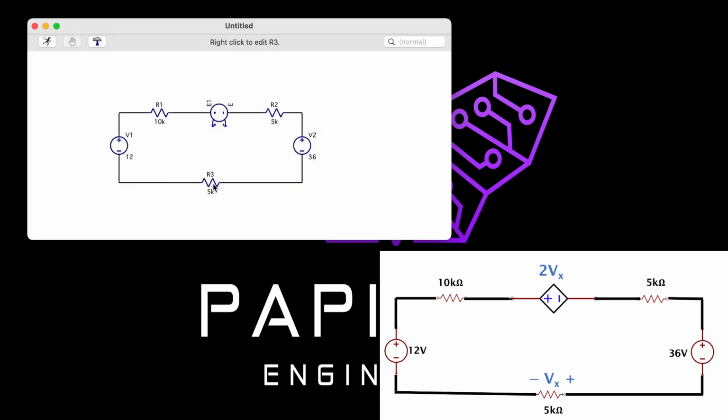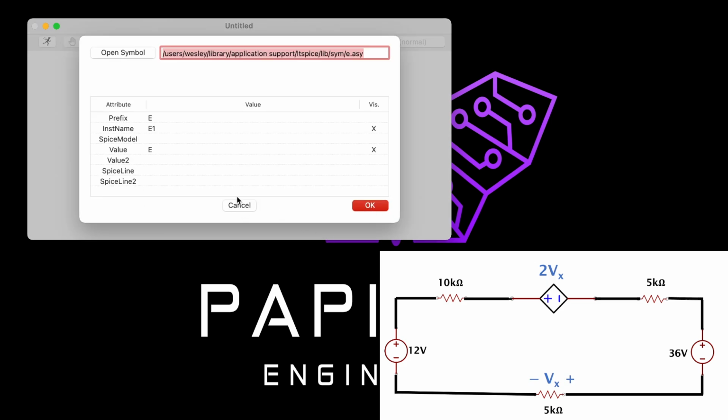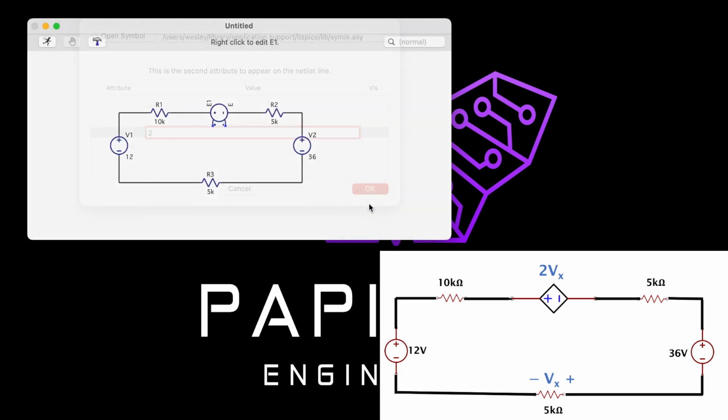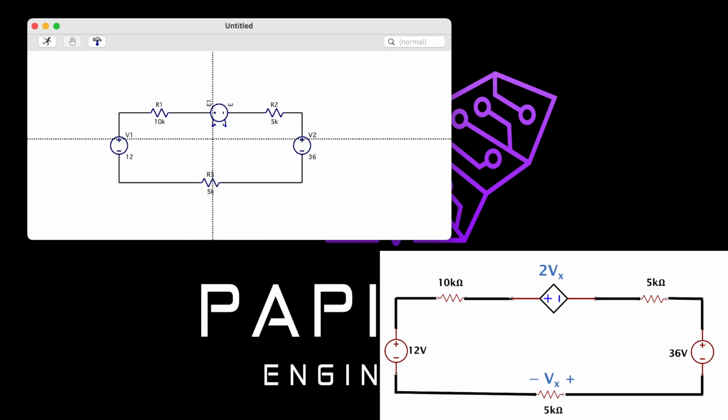So once you have that, we're basically set or close to being set. Notice now I'm going into our voltage control and I'm changing the value. Why again? Because the gain, which is our multiplying factor, is a factor of 2 for this dependent source. So what is it dependent on again? A 5K ohm resistor. I'll go over the math and the actual problem solving if you hang tight for the next few minutes. I'll certainly go over that as well.